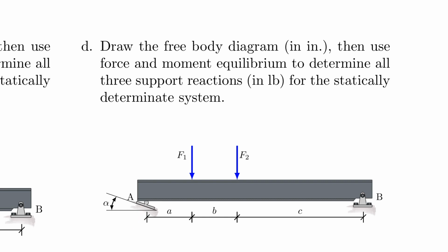But there's definitely a force that is perpendicular to that surface. Sometimes there's also one that's parallel to the surface. But understand that in this case, the surface defines in which direction you have to find your support reaction. And so these two forces here actually act a little bit different if the support is angled. I mean, the forces act the same, but the support reaction reacts slightly different. But you can use your moment equilibrium to find the support reaction on both sides.